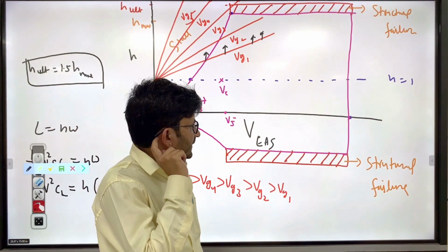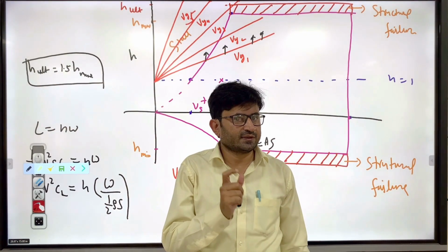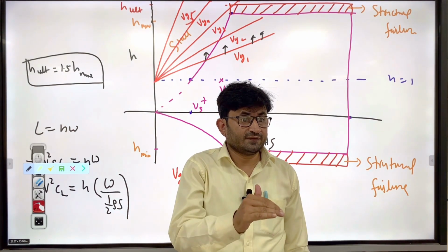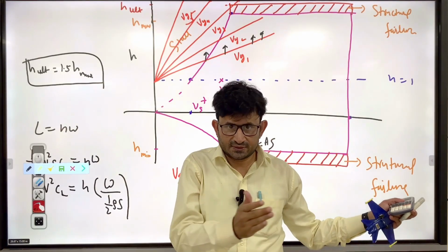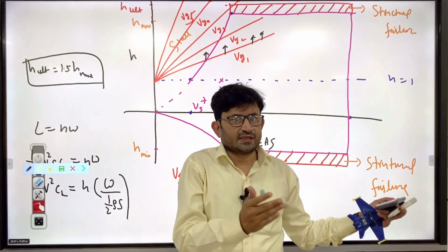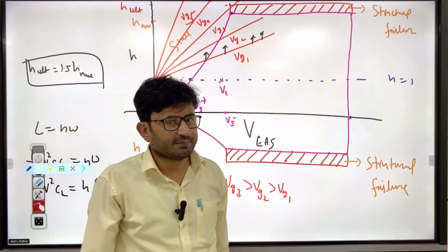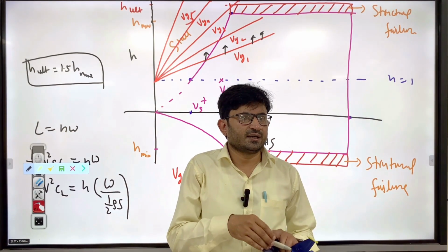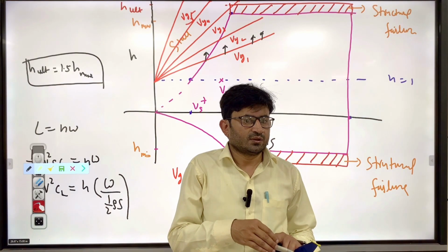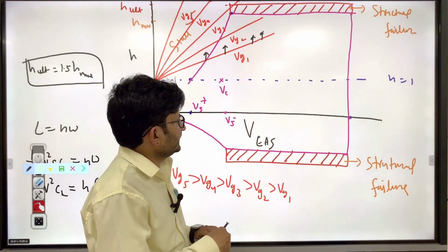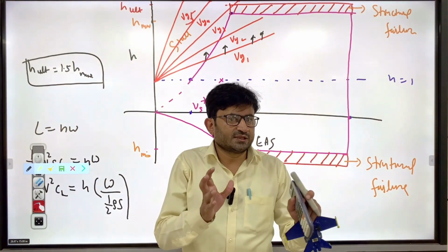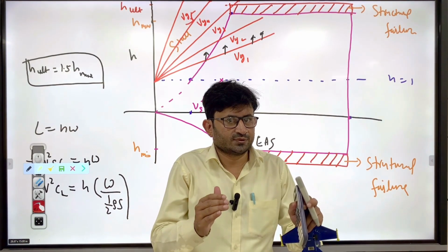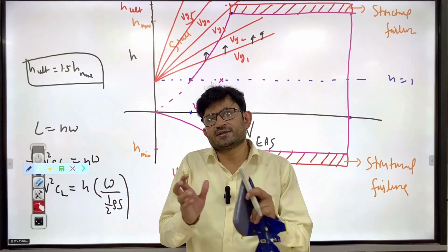And if you have any doubt, please ask me. I will try to explain to you. In this lecture also I have taken one small UAV aircraft and one commercial aircraft. Commercial means Boeing, Airbus A320 I have taken as example, and one small light UAV comes under the small UAV configuration category. So by comparing these two, you can see in which case the gust is more sensitive. So it is the small UAV case, not the commercial case.